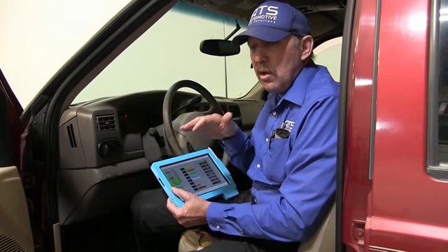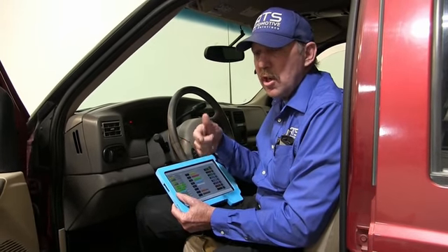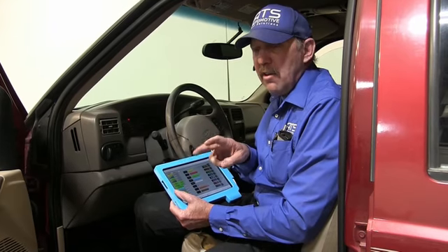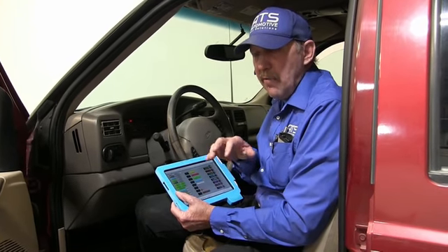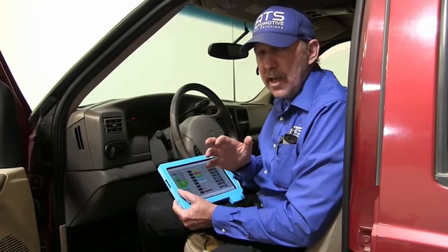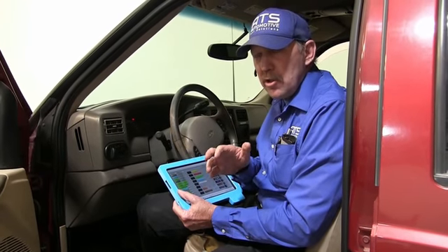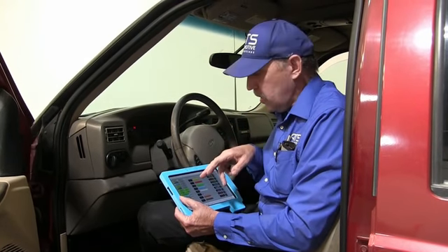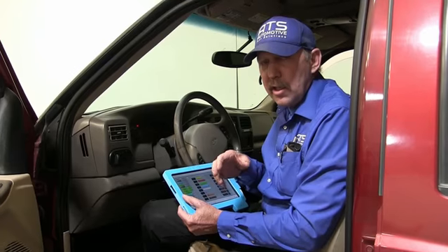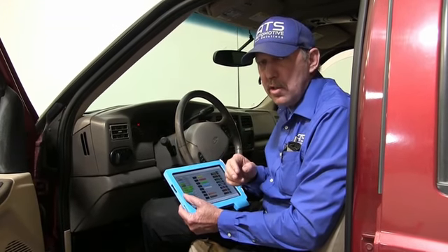You're thinking that when you're going down the road, the transmission starts to slip, and I have a different count between the two sensors, input and output, and then the tranny slipping, so I've got to protect the tranny. And to protect the tranny is to cut the torque from the motor. So I want to get a scan, I want to get my scope, and I want to get on this output speed sensor. I want to look at that signal to start with. So let's go ahead and do that first.